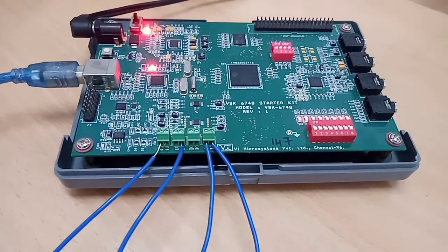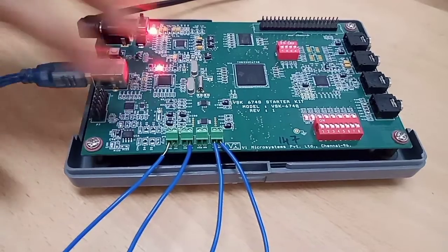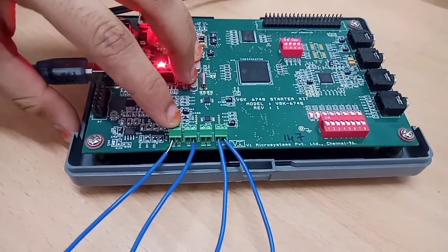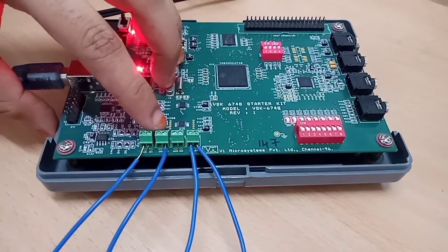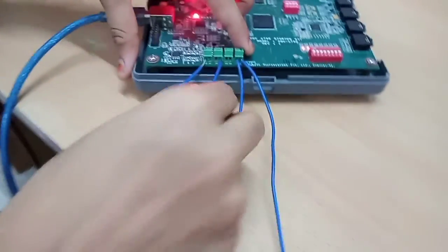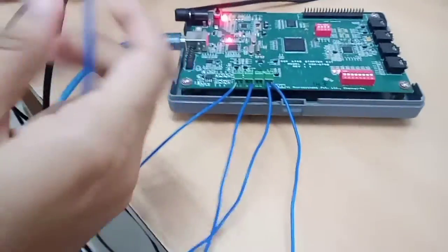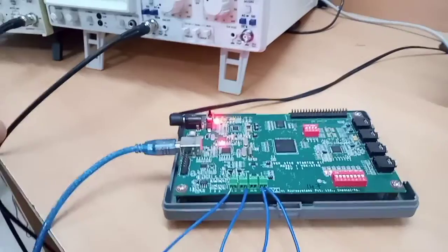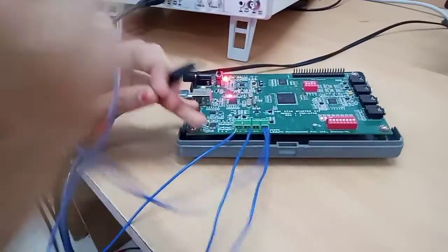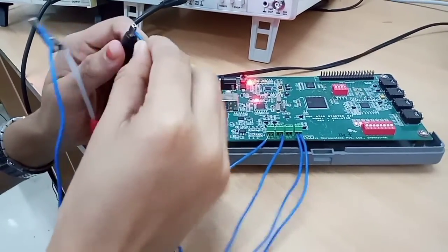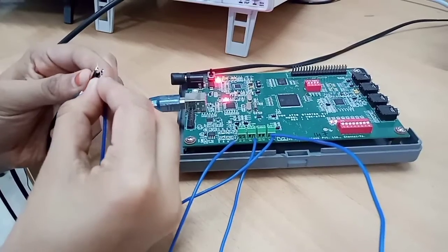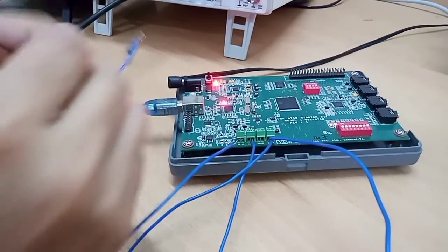Now, in the processor, we all know that there are 4 ports. The first port is ADC, the second port is DAC, and the last 2 ports are for ground. For the FG, the positive connection is given to the ADC channel and the negative connection is given to ground. And for the CRO, give the positive connection to the DAC channel and the negative connection to ground.